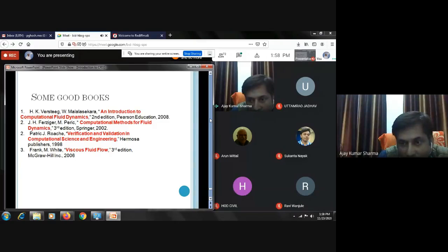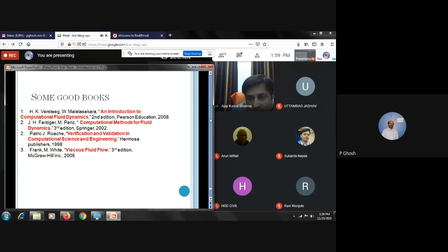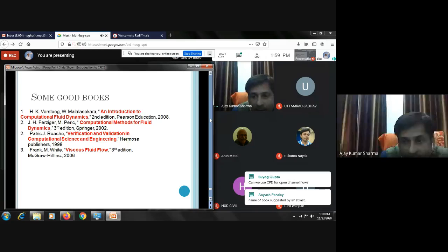Another one is from Ramakrishna. Okay, Ramakrishna, I explained that very clearly, but I am repeating that again. Say, if you pose a problem and you are not getting a convergence, you have taken a geometry, properly imposed the flow physics, given the boundary conditions correctly, and you are sure about that, then you should doubt the under relaxation factor. The first doubt, if you are not getting convergence, is your grid and boundary condition. First is not the under relaxation factor. If you impose those two things correctly, then you should think about the under relaxation factor.